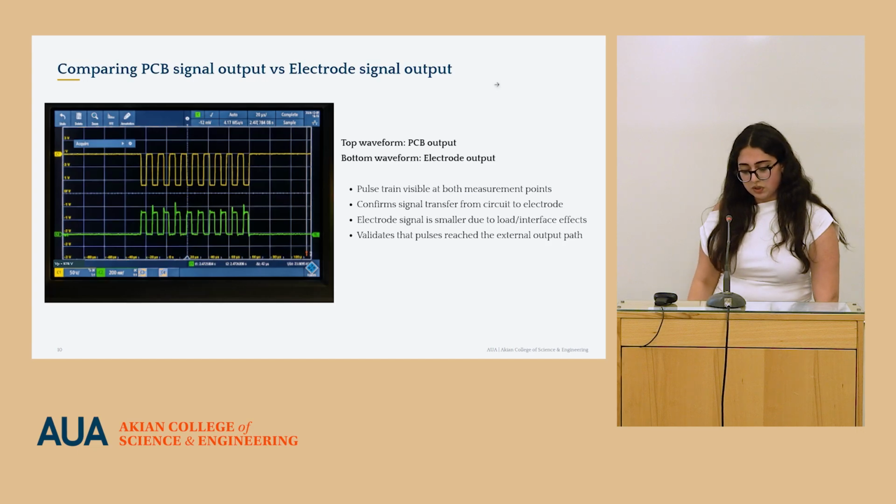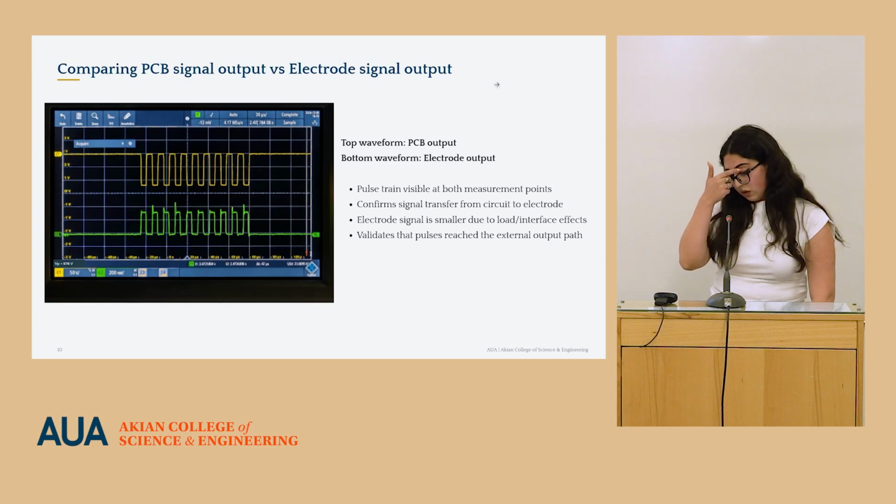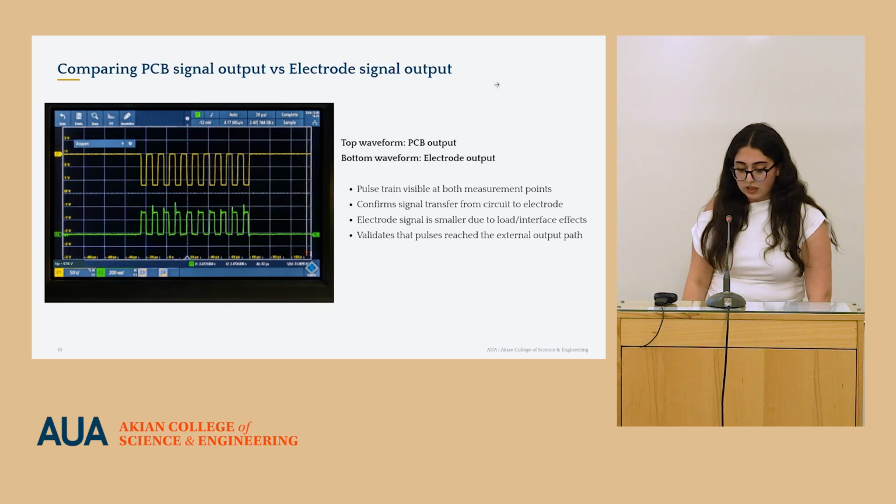There's a little bit of noise for the electrode signal output, and that could be due to the connection, for example, how we connected that electrode to the PCB. And yes, it validates that pulses reach the external output path.